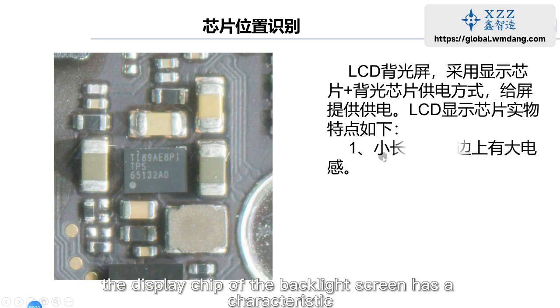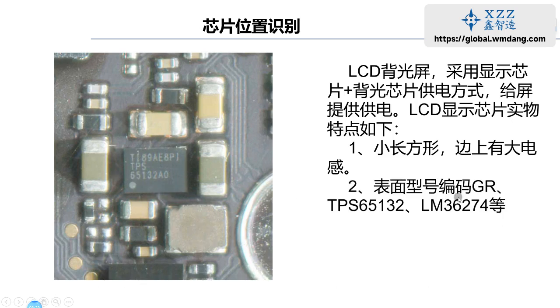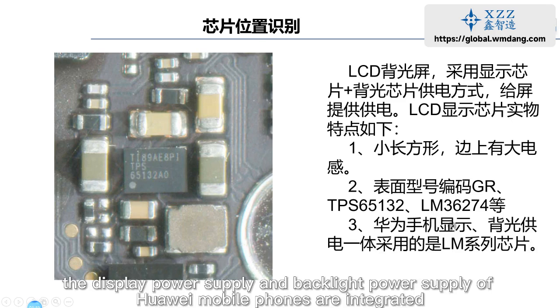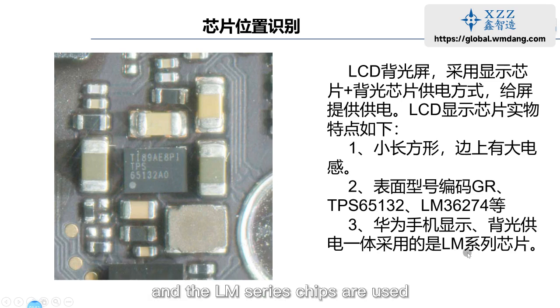The display chip of the backlight screen has a characteristic. It is generally a rectangle with a large inductor on the side. The common models include GR, TPS, and LM. The display power supply and backlight power supply of Huawei mobile phones are integrated. That is to say, the display power supply and the backlight power supply are completed by one chip, and the LM series chips are used.